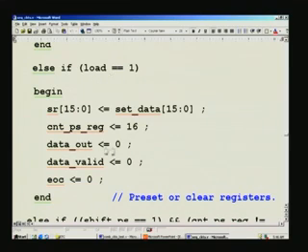That is what we want. And we also have a counter inside. Here that counter is preset to 16. This keeps track of the number of bits that have been sent out. Say you want to send 16 bits of information, that is the reason why it is 16 here. And data out and these things are not to be active as such, so we just retain them as 0.